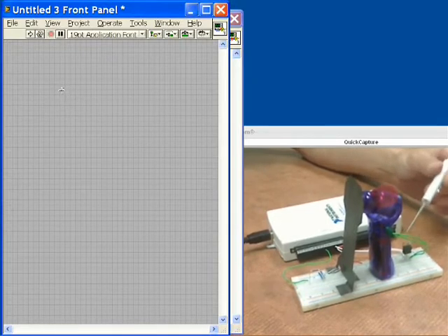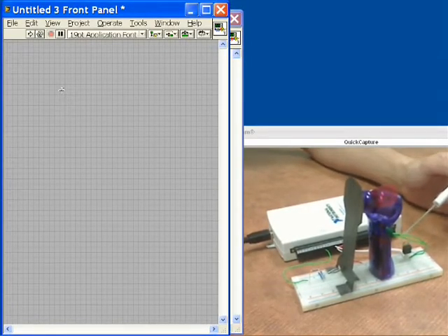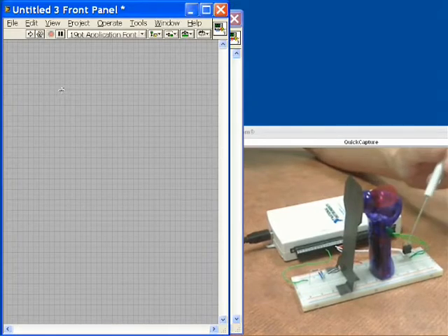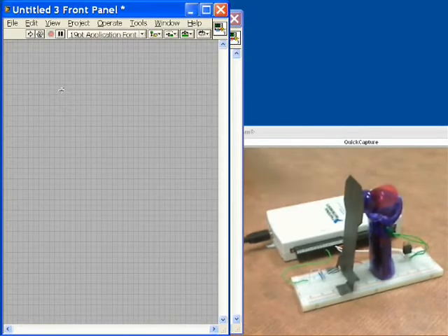So instead we're going to use the batteries that are inside the fan to power the motor, and we're going to modulate that with a power transistor. So we take the analog output coming into the base of the power transistor, and then in the emitter and the collector we're just using that to control the amount of power in the fan itself. So as we change the analog output voltage, the power of the fan will change.